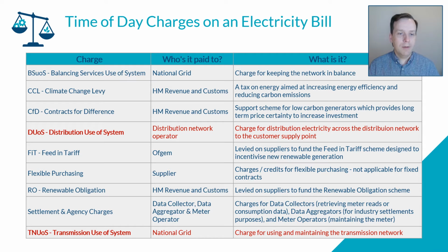So here in the UK we have at least 9 individual charges or penalties based on the kilowatt hours used, but also on your connected capacity. So somebody with a connected capacity of 1000 kVA, kilovolt amps, would be charged more over somebody with a connected capacity of 500 kVA to the grid.